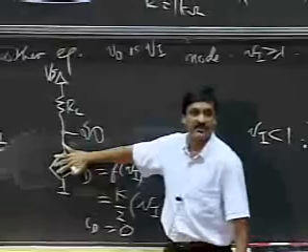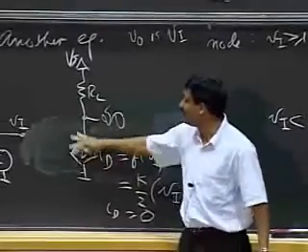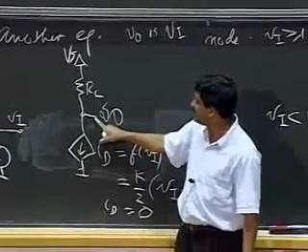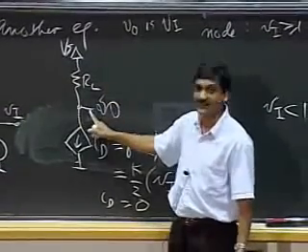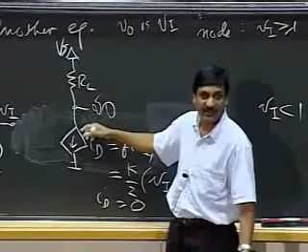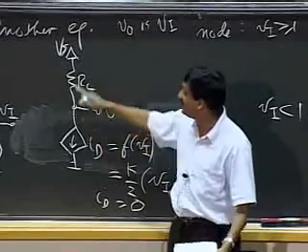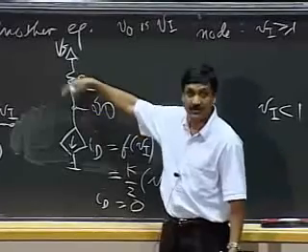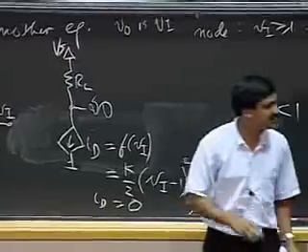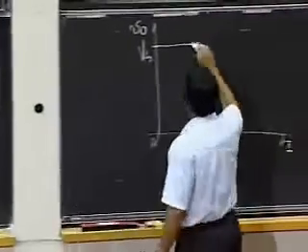As long as the current here is 0, this is like an open circuit here. If this is an open circuit, then effectively V naught is simply the voltage Vs. V naught simply appears here. If you want to grunge through KVL and KCL, go ahead. Vs minus RL times the current is V naught, and the current is 0, so it's Vs. So this is simply Vs.